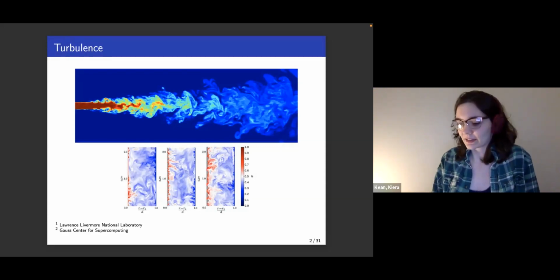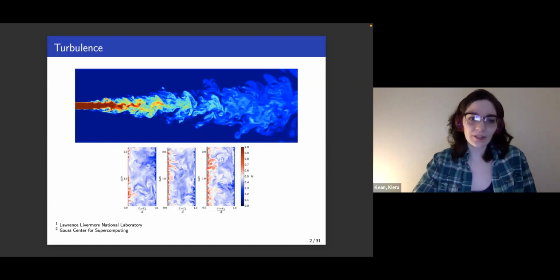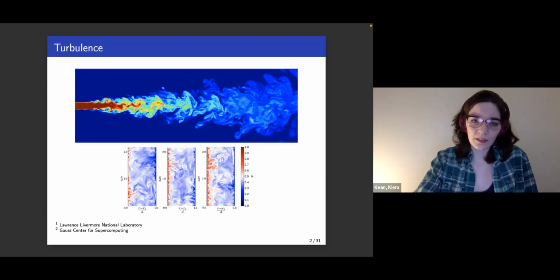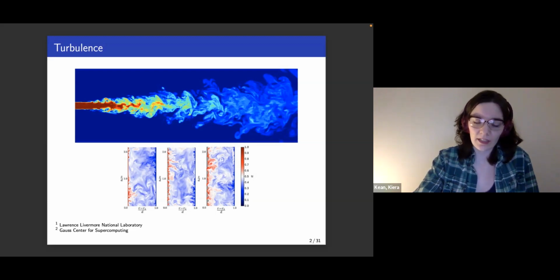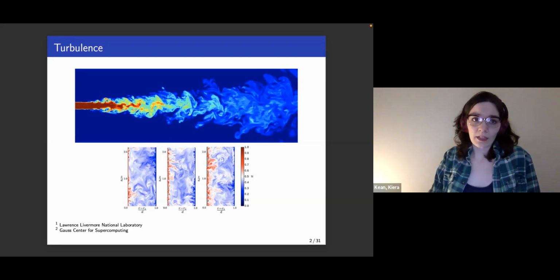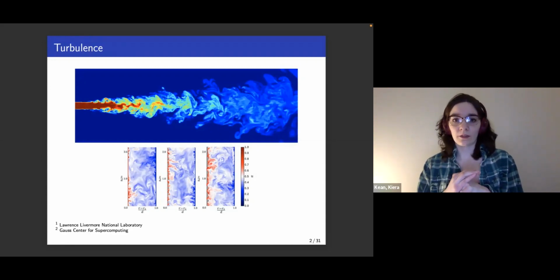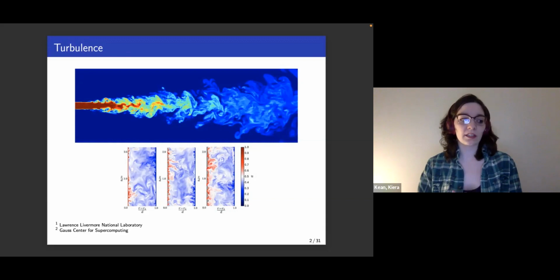that are relevant in many applications. So pictured here are two direct numerical simulations of turbulent flows, both shear flows, a jet entering a tank, and cross sections of Taylor-Couette flow, which I'll discuss more later. We can do this for smaller problems, but again, for larger problems, we look for turbulence models. So we will truncate the scales that we directly calculate and model the effects of the unresolved scales.